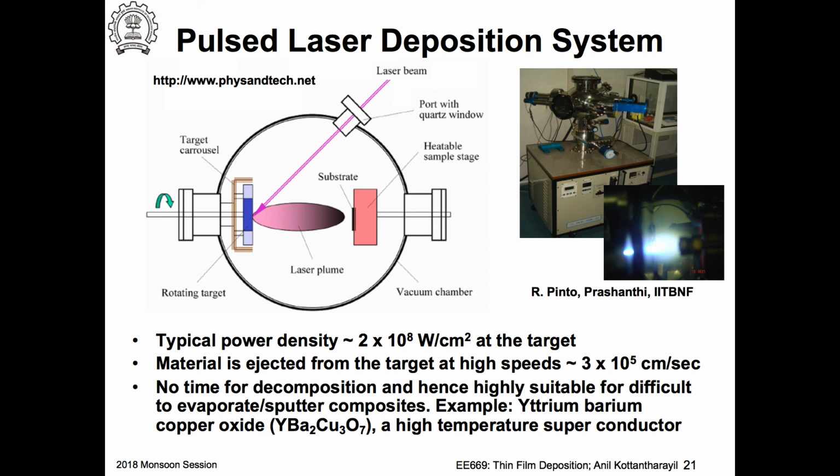So the laser beam will be focused, and as a consequence, the power density there would be very, very large. So the target actually gets evaporated spontaneously because the power density is so large. The local temperature will be fairly high, and it's very interesting. You see that here. So material gets ejected from the target surface and gets transported to the substrate where you want to deposit it.